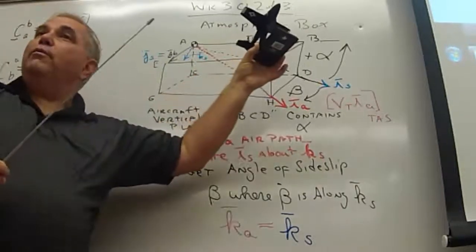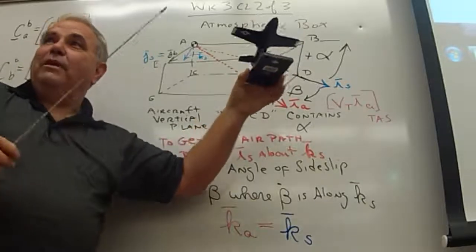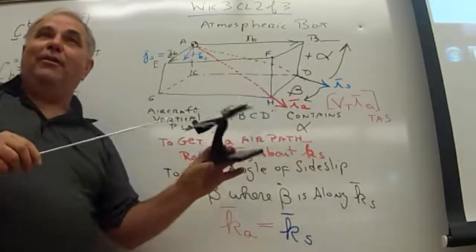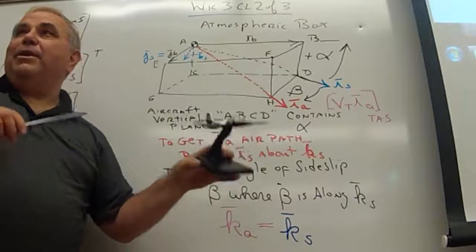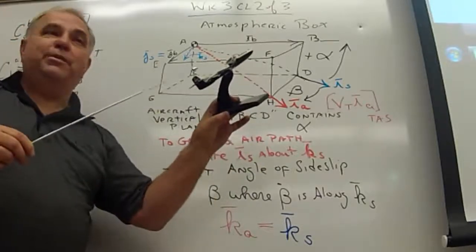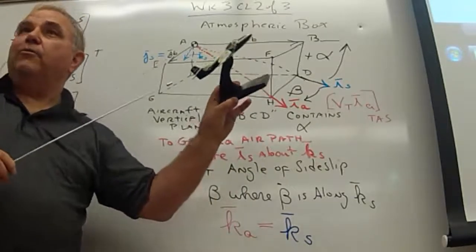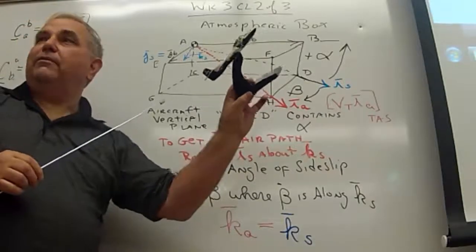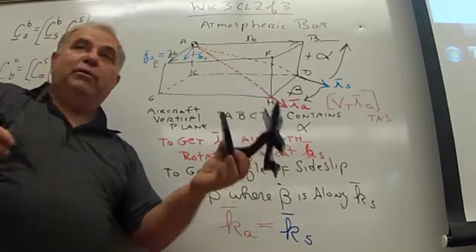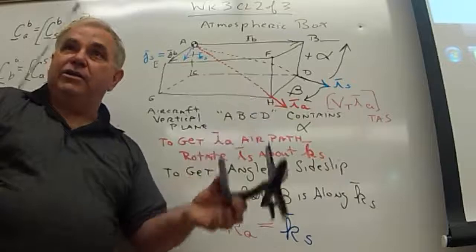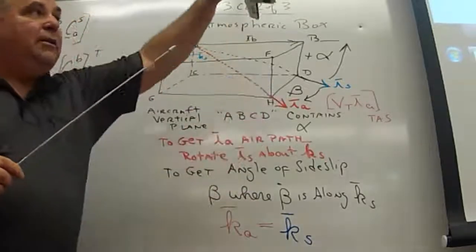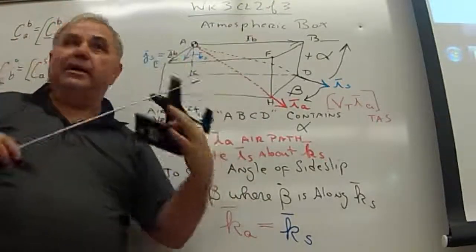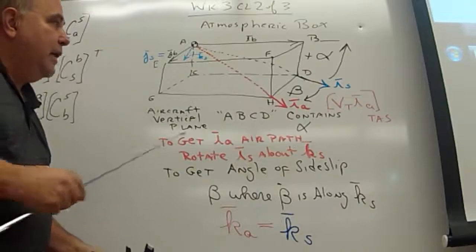As long as he's below maneuvering speed, if he's above maneuvering speed, then he won't stall, he'll pull the wings off. But when he gets to the stall angle of attack at maneuvering speed, he'll stall the airplane right at the structural limit for the wings. So you should remember what maneuvering speed is, max G load, how that relates to the minimum radius of turn. All this is kind of being tied together now, and then how it relates to alpha.